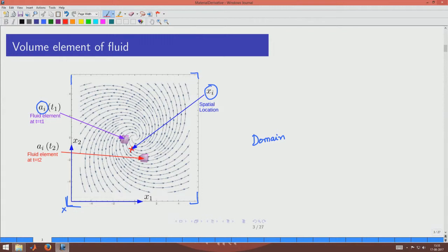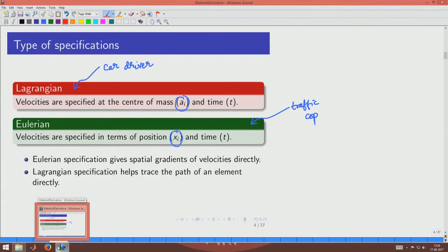So, the Eulerian specification allows us to have the complete information about the velocities as function of space as well as a function of time, and by default if we are not talking about the specification, then we are referring to the Eulerian specification. Okay, so, this is the way we are going to specify in this particular course, and in what way these are going to be used.